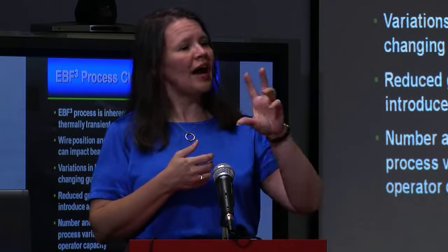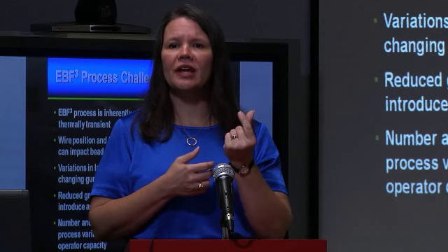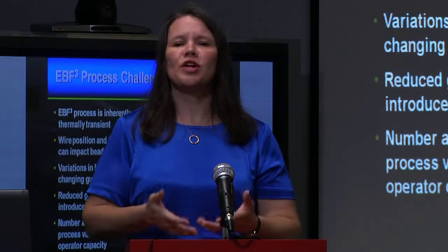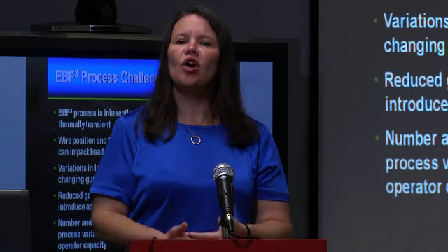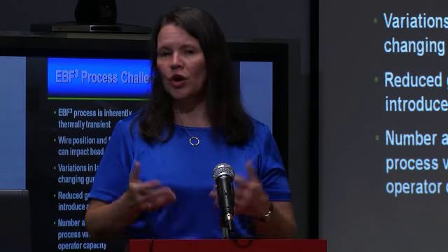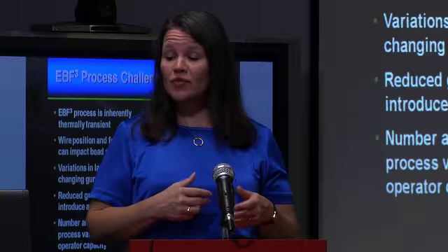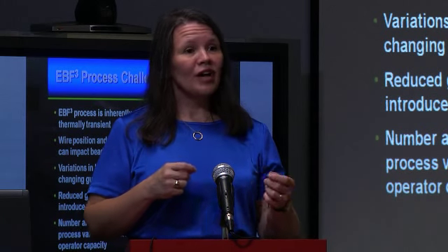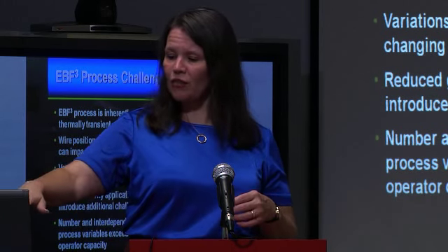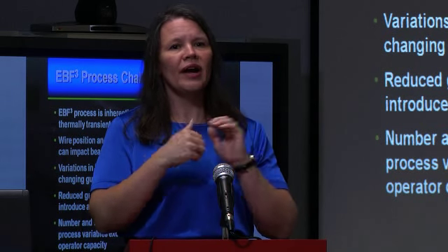You can get a much higher build, much more regular bead width, and that's desirable because it's predictable. It's something that we know we can get the same thing time after time after time, which is going to be important for putting this into application. The bottom picture just shows some of the places where we have flaws. You can see about a third of the way up there's a layer that doesn't look quite right.